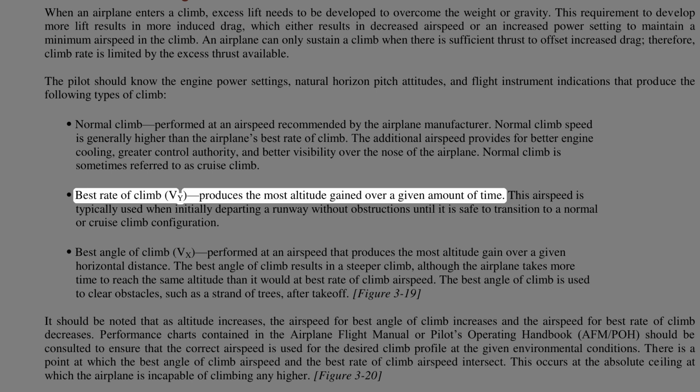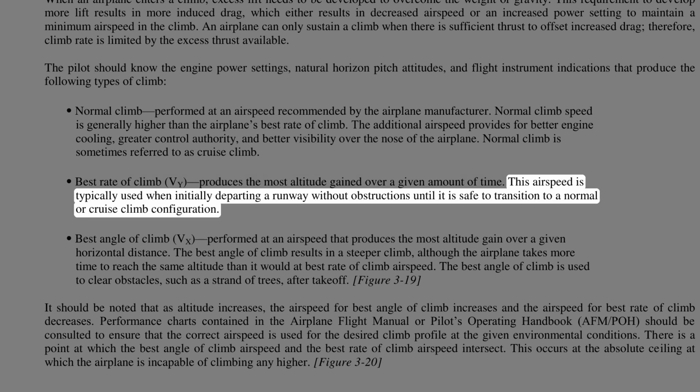Best rate of climb, VY, produces the most altitude gained over a given amount of time. This airspeed is typically used when initially departing a runway without obstructions until it is safe to transition to a normal or cruise climb configuration.